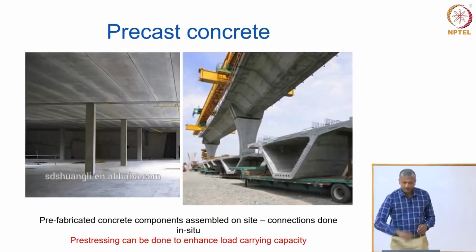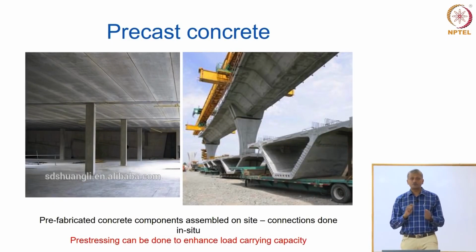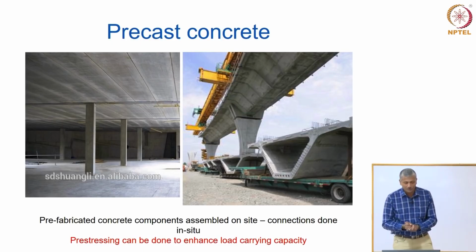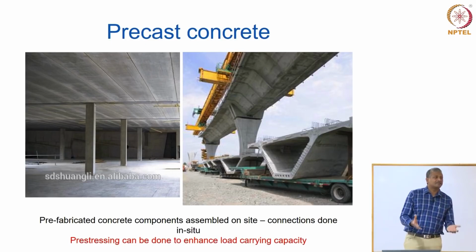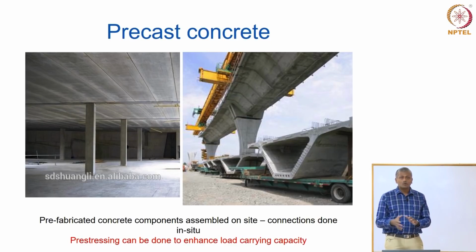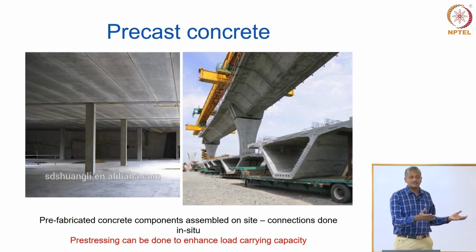Right. Now, when you slow down your process because you need to marry steel and concrete, what you can also do is try to look for methodologies by which you can strengthen the concrete itself and make it respond in a positive way against tensile loads too. And this has been accomplished by the use of pre-stressed concrete. Okay? You'll learn later about what pre-stressing is and how it actually increases the load carrying capacity of concrete. But overall, this pre-stressed concrete belongs to a segment of concretes called precast concrete.